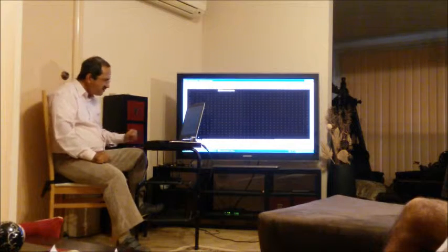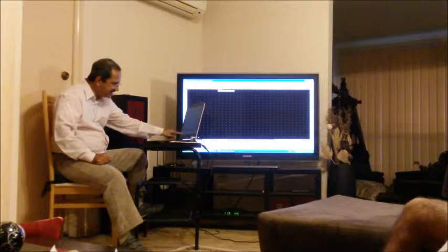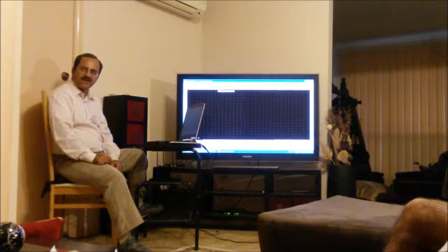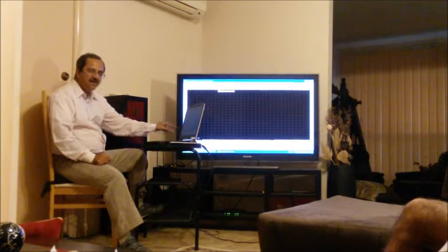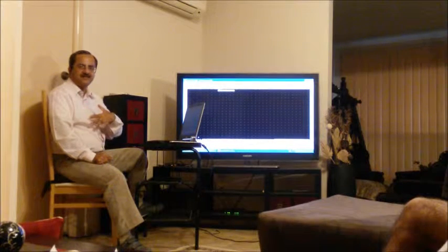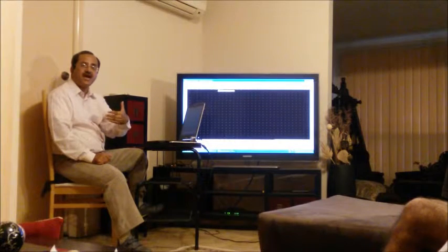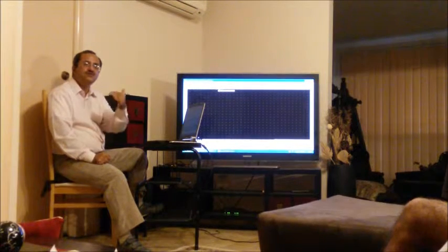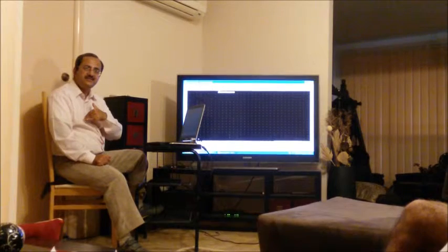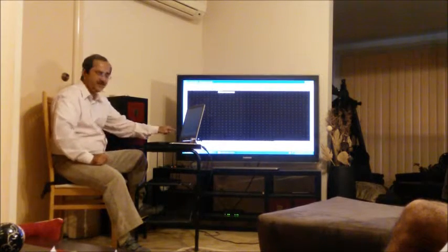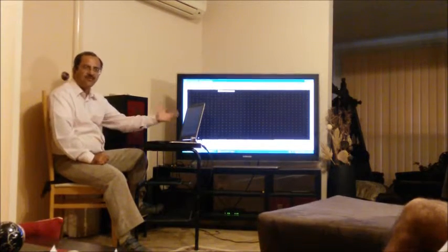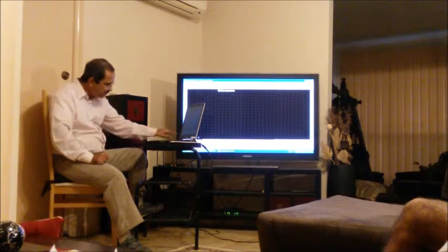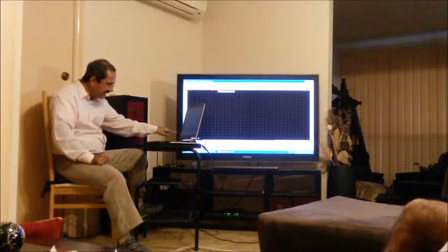Alright. Now if you look down here, there is a strip which says command. This area down here is the interactive area. This is the area which AutoCAD is using to talk with you. And if you want to talk to AutoCAD using the keyboard, you will type in this area. There are a number of ways you can talk to AutoCAD, but AutoCAD will talk to you only through this area. So if you read what is written down here, it is saying line.